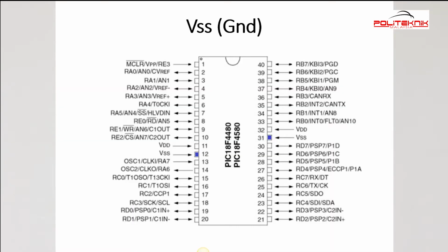Then, 2 pins are used for the ground. In chips with 40 pins and more, it is common to have multiple pins for VCC and ground. This will help to reduce the noise or ground bounce in high frequency system.